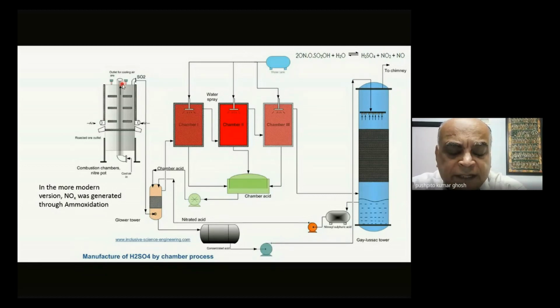We know that the NO2 catalyzes the oxidation of SO2. We also know that when you are passing air through this, that air is being utilized to supply the oxygen for the oxidation. But all of the oxygen is not necessarily consumed in this first part. So there will be quite a bit of oxygen which is passing through in the outlet, besides, of course, nitrogen, which will always be present in air.